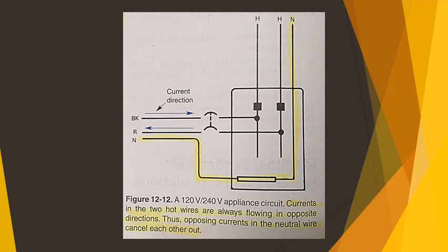That is basically the limit of amperage that you would like the home to have. Each branch circuit should have its own OCPD, or overcurrent protection device, and those are the ones that protect the house and the equipment and the persons living in the house from the effects of overcurrent, fire, overheating, and damage. Not so much the main breaker.